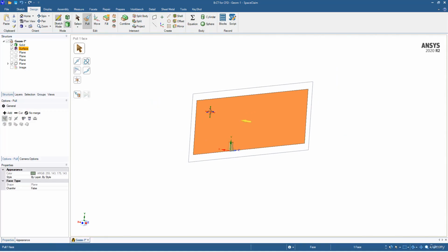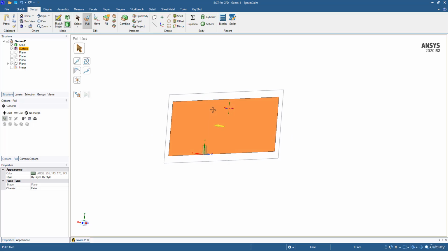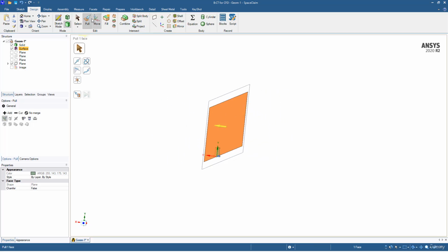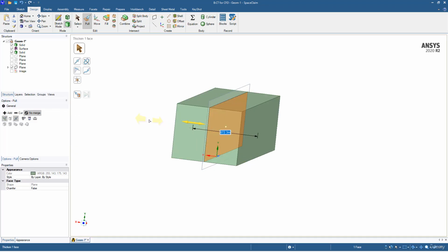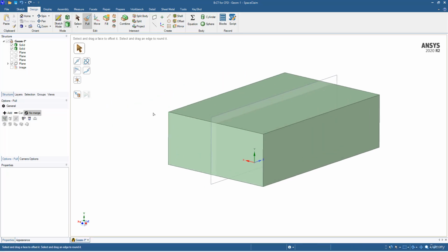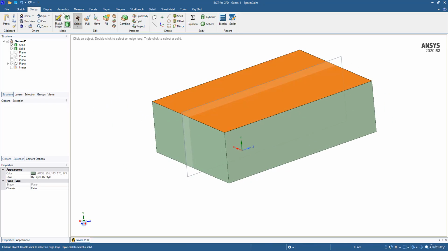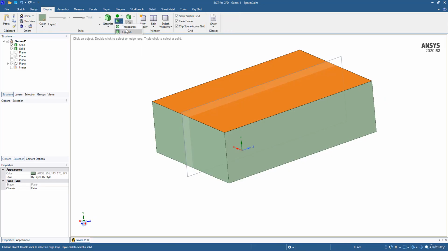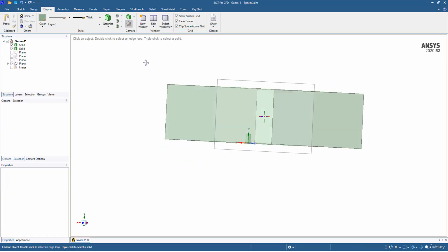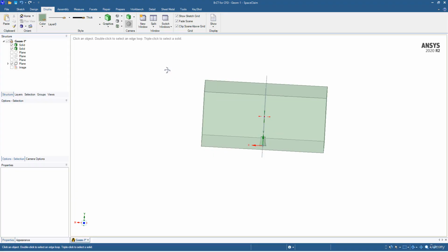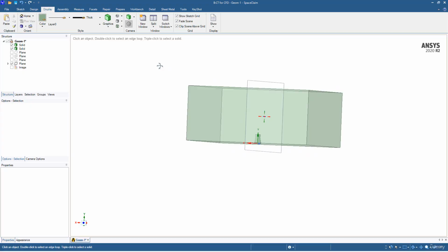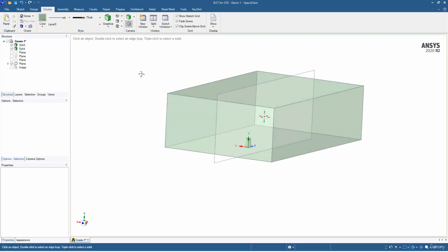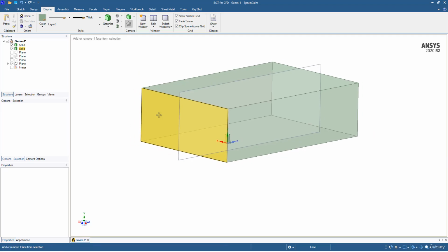So I'm just going to make the domain size on both sides, and that would be equal to 800 on both sides. So I will use this command, pull both sides, and no merge. Total will be equal to 1600. Apply. And now I just want to see how this will look with this domain, so make it transparent. I guess that on both sides this is okay. On the top side this is also okay, and the same is the case with this inlet part.